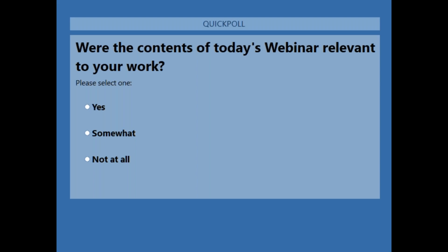There are some questions about Bentley AutoPlant. Can Plant 3D integrate with Bentley OpenPlant or AutoPlant? Yes, we could integrate the Bentley AutoPlant data into Plant 3D, and the specs relevant to tools like OpenPlant, AutoPlant or CADWorks could be converted into the spec facilities inside Plant 3D. So we have that flexibility of spec conversion and connecting it to Plant 3D.